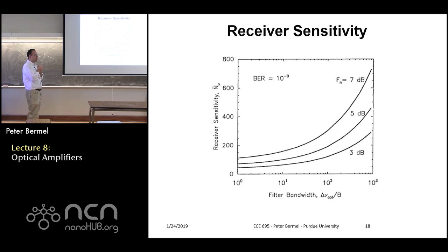Usually something on the order of 10 to the minus 9 is considered to be reasonable. Of course, some applications may even want lower, but the idea usually is that if it's very important information, there should be some software overlay on top of that hardware to basically correct those rare errors. This is very common, like with TCP/IP, which is used to fetch web pages, that if there is some sort of error, then you ask for a retransmit rather than just accepting incorrect information.